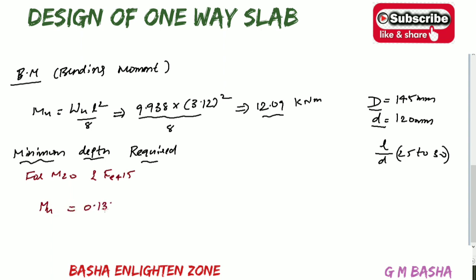That is 0.138 fck b d square. Here we know the Mu value, which is 12.09, and we are considering that value in terms of mm, and 0.138, fck will be 20, and here b.